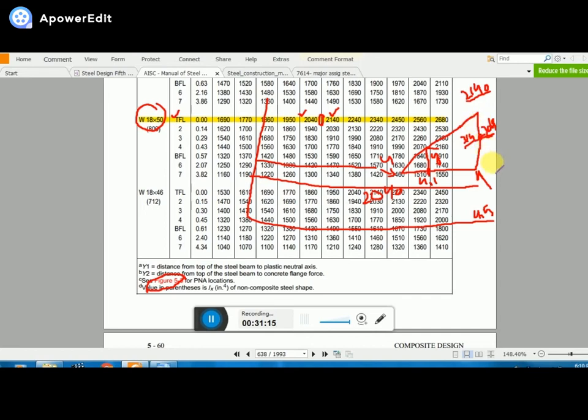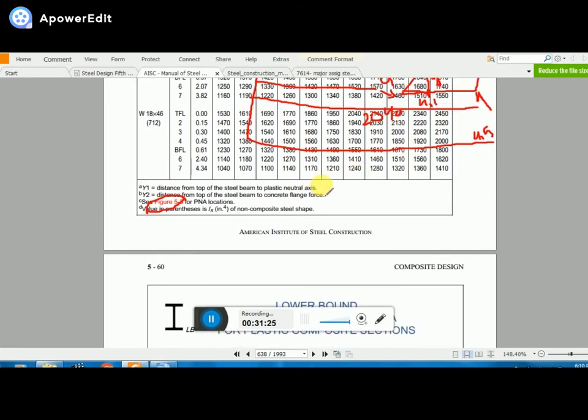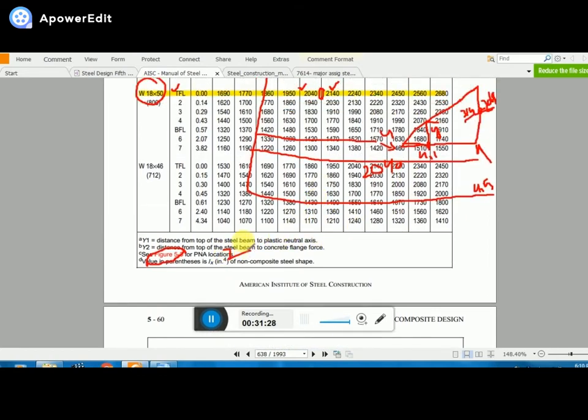Now, using the similar triangle rule, perpendicular over base equals this small perpendicular over the small base. So the perpendicular, 2140 minus 2040, divided by your base, 4.5 minus 4, equals, by the similar triangle rule, y divided by the smaller distance, which is 4.1 minus 4.